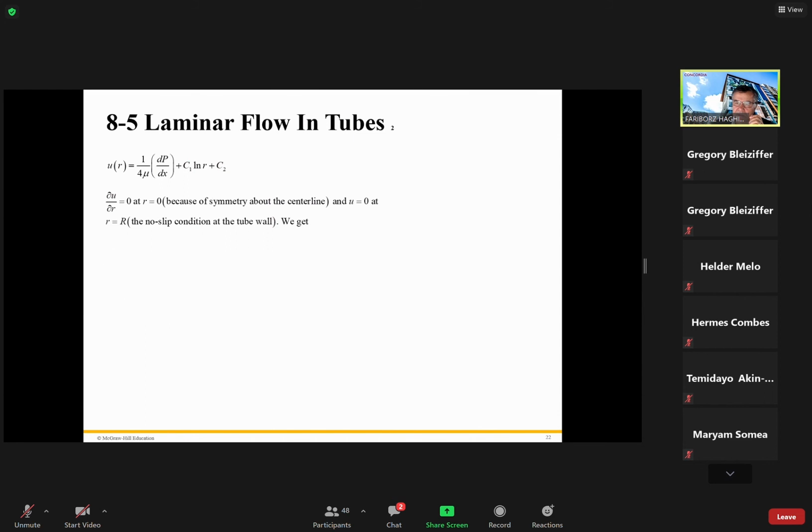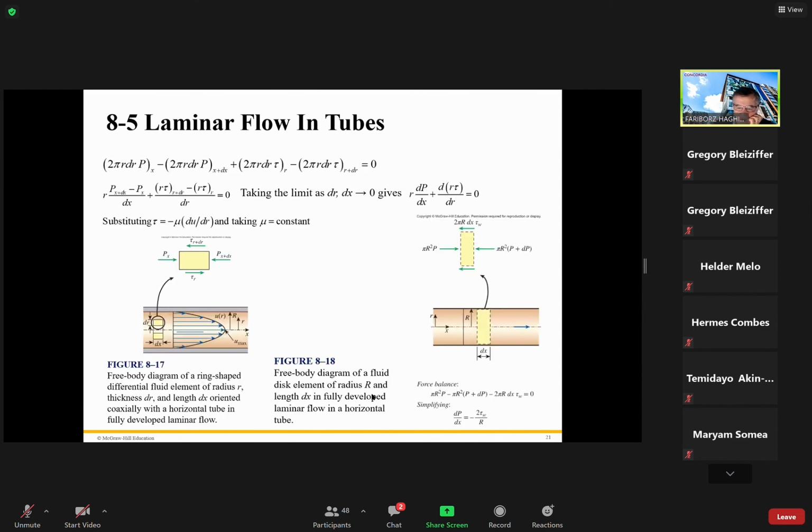If I find the one here. Look at here. The temperature profile is either maximum at the center if we are dealing with cooling, or the opposite if we are dealing with heating. In the case of cooling, the temperature at the surface is lowest and at the center is highest. If I'm doing the heating, the temperature at the surface is highest, so this becomes the opposite direction. But since we are assuming R is equal to 0 here, and R changes, it becomes symmetric. The temperature on this side is exactly the temperature on this side. Yes. Okay.